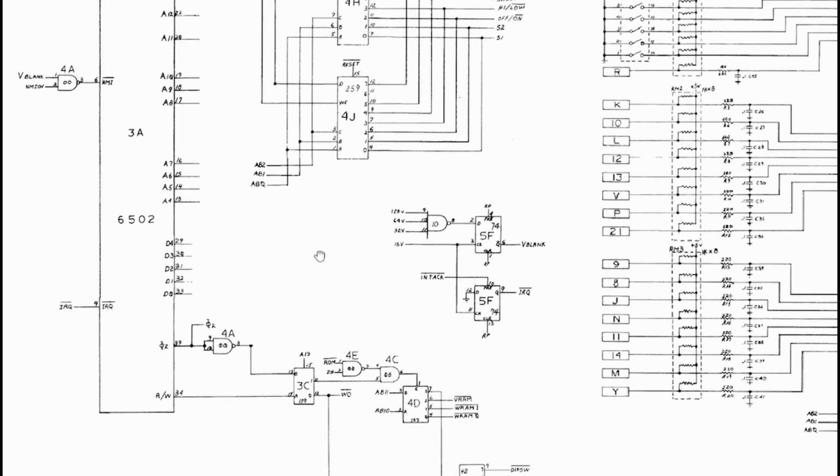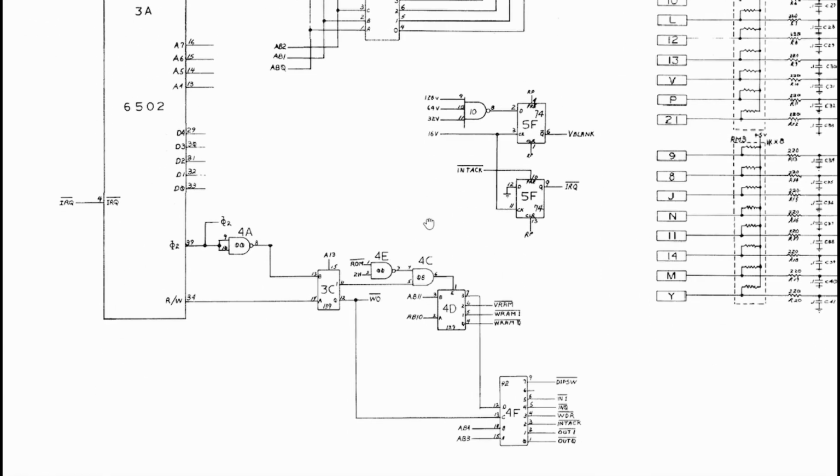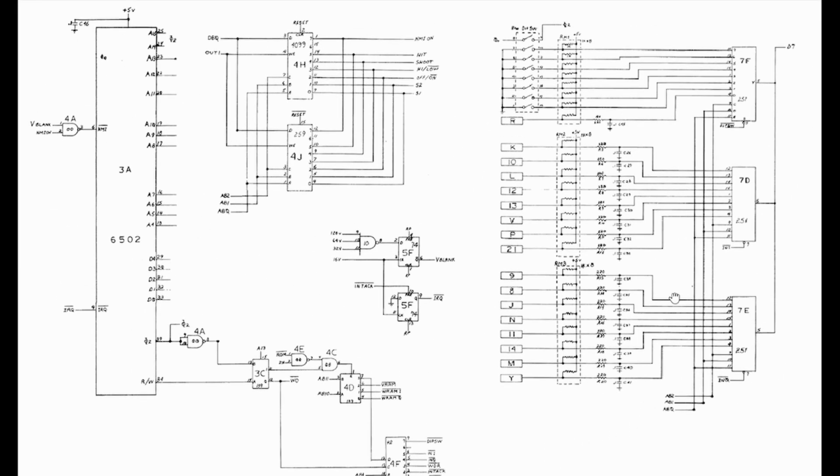This diagram is the schematic of the game, with only the relevant parts for the interrupts or those related to the game controls showing. We've got the CPU, the 6502, with the IRQ pin and NMI pin, and also the circuitry in this lower area that's used to select the correct part of memory to address, or to address the input or output peripherals, using the 74LS42 chip that we've seen before in the addressing episode. On the right hand side here, we have the 3 chips that enable input interfacing, and the chips to the left here that allow output interfacing.